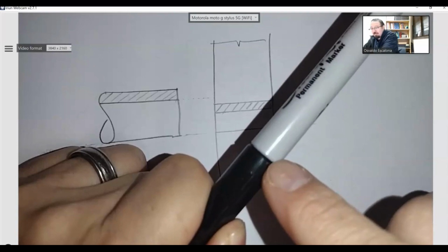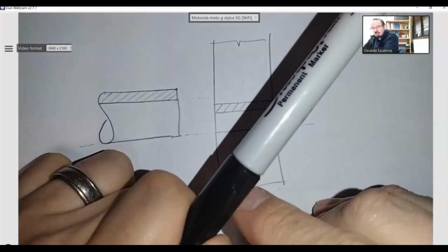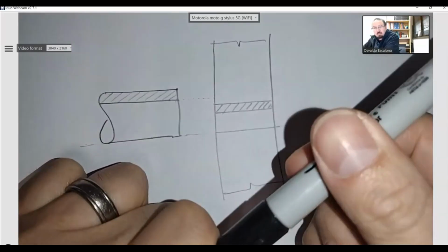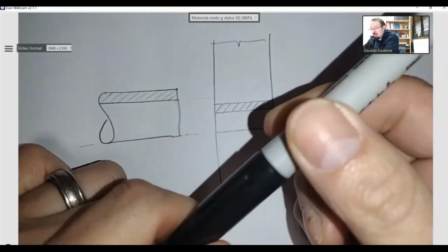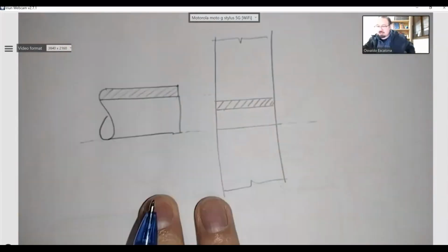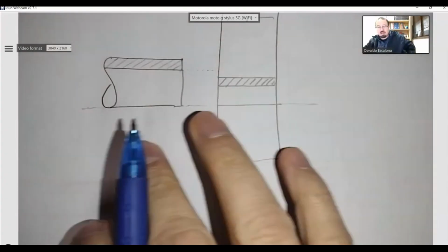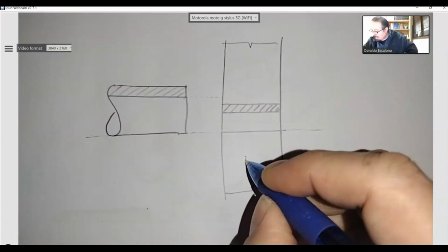For an interference fit, I'm going to have to mess with the temperatures such that when it fits, it will never be able to come off. And if I take it off, the thing is going to fail; I'm going to damage the part. How do I do that? Very easy. If I want to make this mate and I don't want it to come apart, I'm going to make this guy hot.